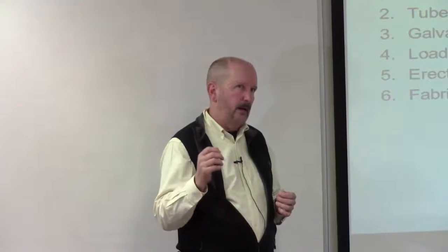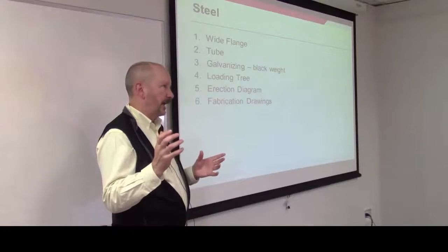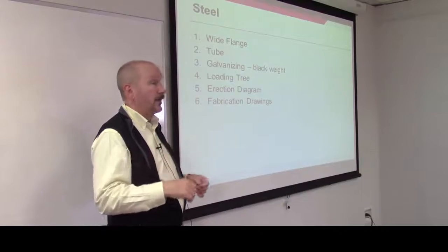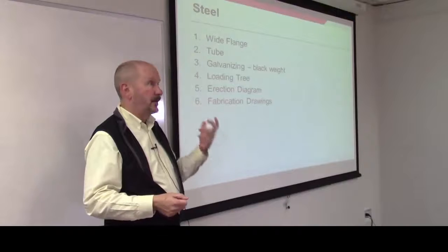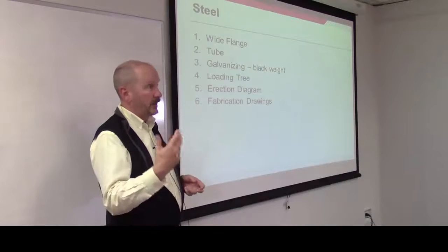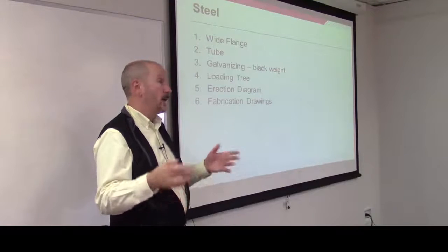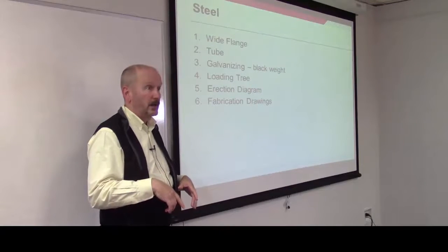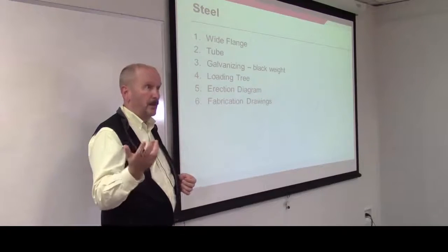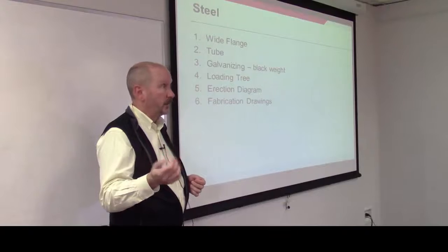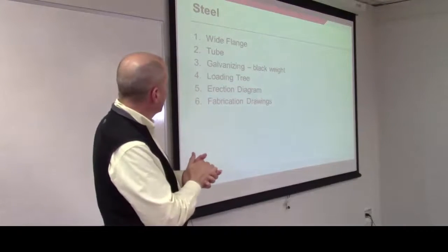And the way lattice is used, you can make towers and structures out of lattice that weigh a lot less, but they take a lot more manpower. So if you happen to be in an era where the price of steel is very high and the price of labor is very low, then lattice will work out. We are not in that era right now. Compared to the price of steel, manpower is pretty expensive. So we don't want to have a lot of assembly out at job sites.